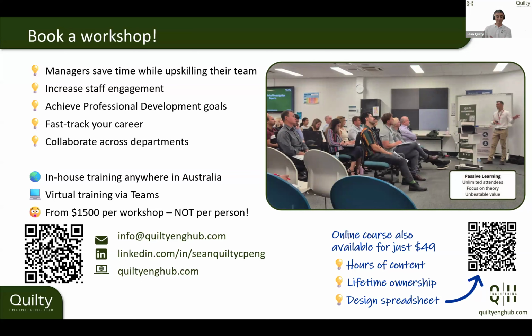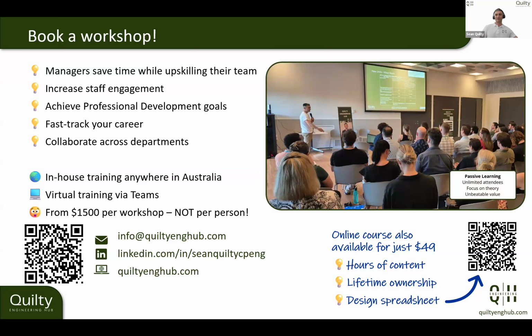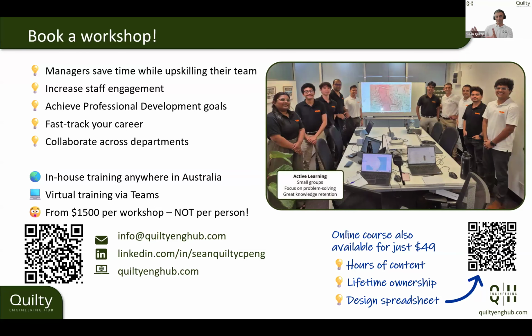So it's very simple. You just look at a different Manning's value. It's very rough. So that Manning's value might be 0.06 instead of 0.03 for a standard grass. So it's twice as rough, or maybe even more. Calculate using Manning's equation. Now, all of a sudden, the velocity is going to be a lot lower, and you think, oh, that's great, it's not going to erode.